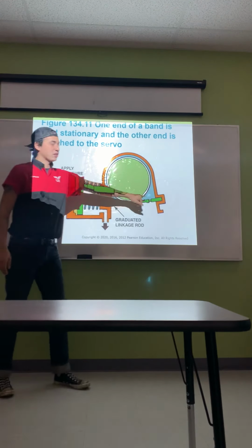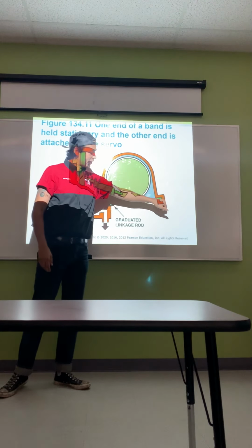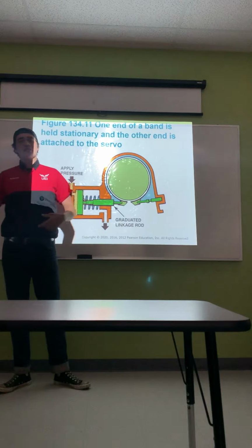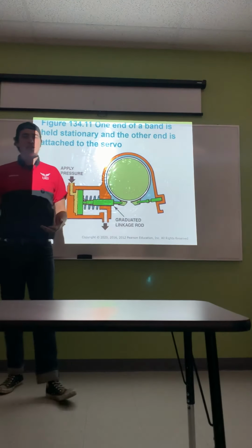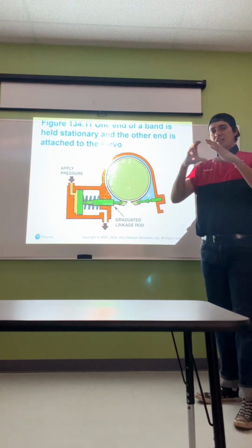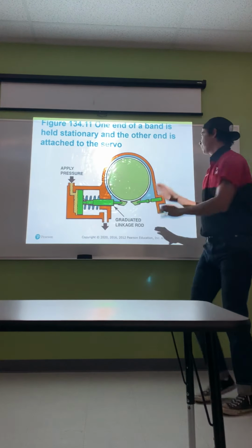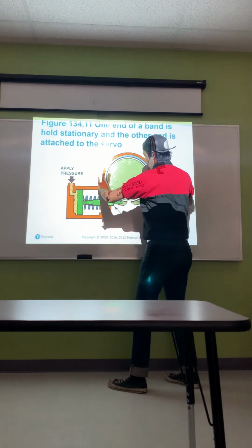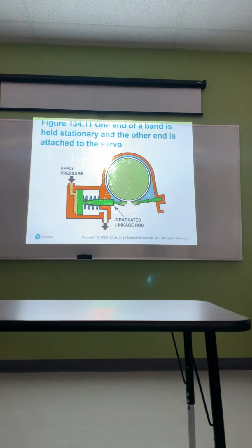And these can be adjusted from the outside. On older style transmissions, you're going to see a little dial out here. You can adjust it because through time, the material inside starts to slip. It slips because it's not grabbing tight enough, since you haven't adjusted it yet. If you adjust it, this works its way in, which makes it smaller. Making it smaller means when it engages, it's going to grab on tighter. If it grabs on tighter, it's going to slip less.